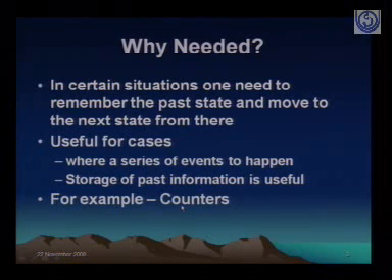Let me try to explain it further: how a sequential circuit is dependent on the previous state. Let's say a counter. So what does a counter do? It primarily does the counting job. Right now the counter is at, let's say, state number 5. Let's say it is a binary counter, so it is counting. So it should move from state 5 to the next state, that is state number 6, right? So this particular circuit is expected to remember the present state, which may be 5, and the future state becomes 6.